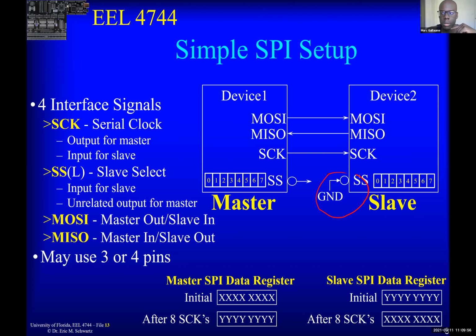Okay. And that's the safest thing. Make it an output. Even if you don't use the output, make it an output, and then it can never cause any problems. But then you've also got an output pin that you might otherwise not have had. So if you ever need it, you've got an output. And that output can be used to connect to your slave's slave select if you wanted it. It can also be used for general purpose output.